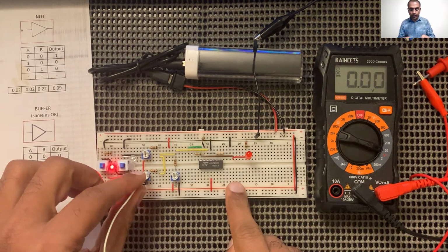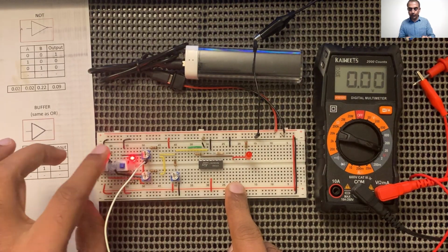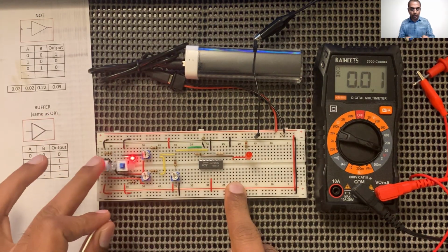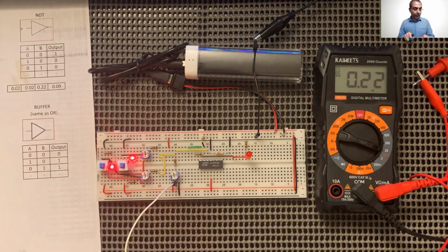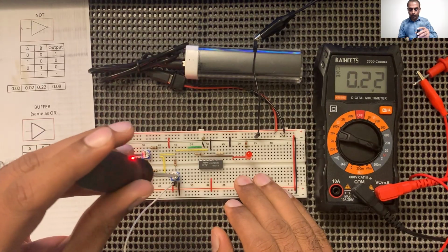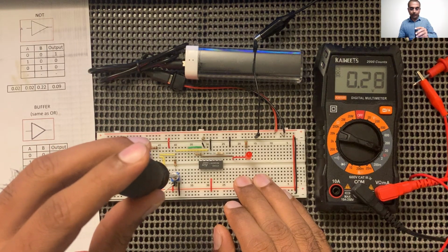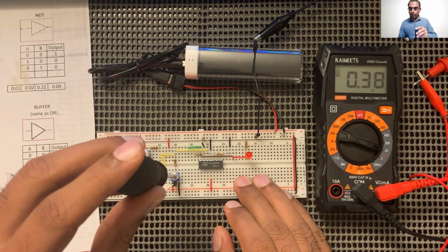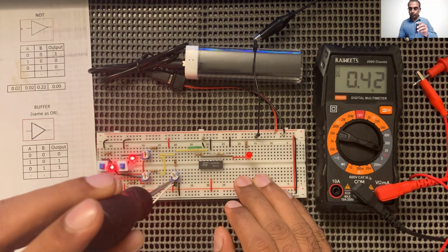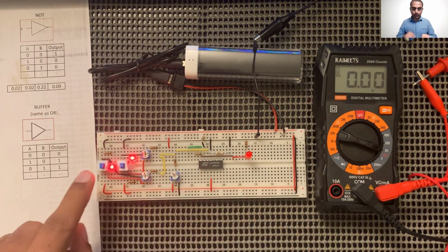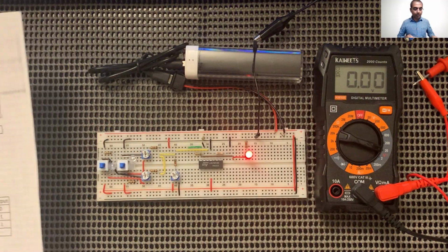We have already tuned these potentiometer A and B to 0, but I'm just checking to make sure they are. And now I can quickly go on to the bias and tune it to 0.42. We're already at 0.22, so I have to tune a little bit to the left and I should reach 0.42. 0.42. That was quick. Okay, let's see if it behaves like a NAND gate.